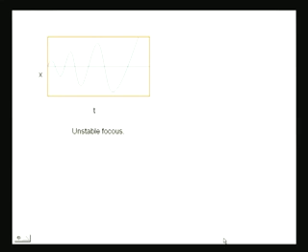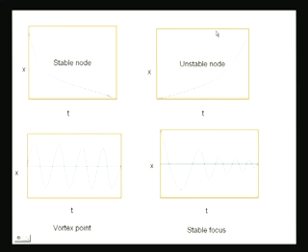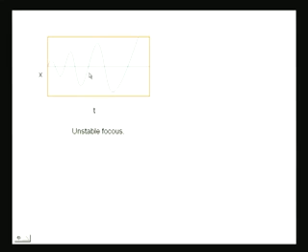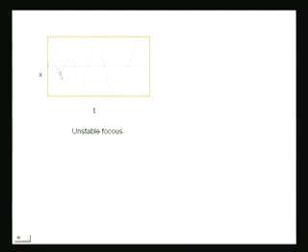And the last one is an unstable focus, where you give a little perturbation, it starts to oscillate and the oscillations start to increase. Coming back to the hotspot question, this is the one that is most seen in hotspots. So, there are two possibilities of instability. One is the second example, where it grows uniformly, and the other is this one, where it grows through oscillations. What is seen in most chemical and biochemical reactors, which we are studying, is that when the system goes unstable, it goes unstable through this unstable focus.